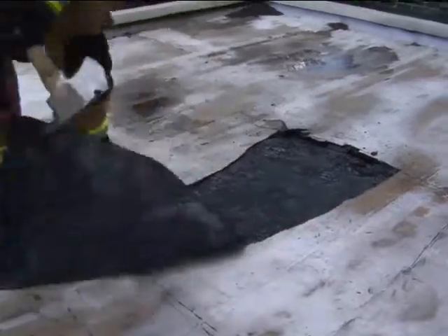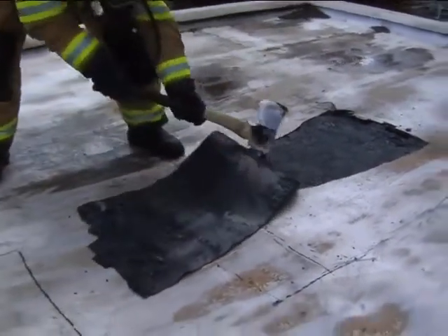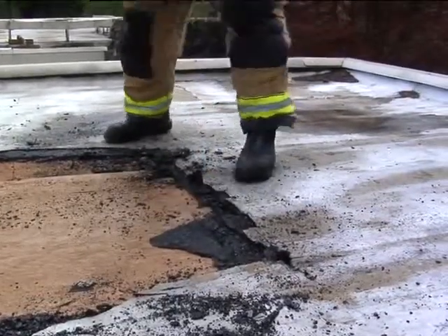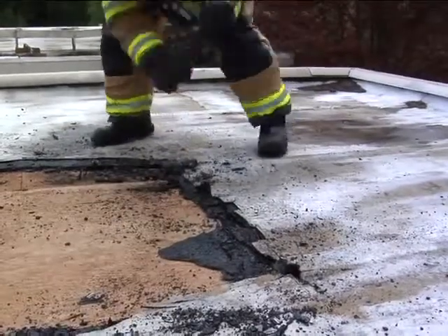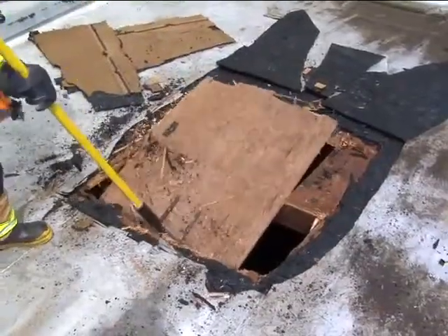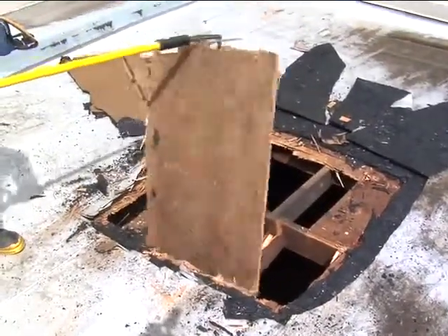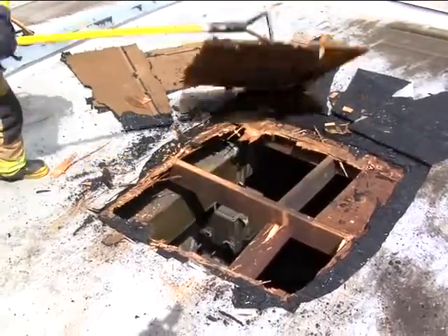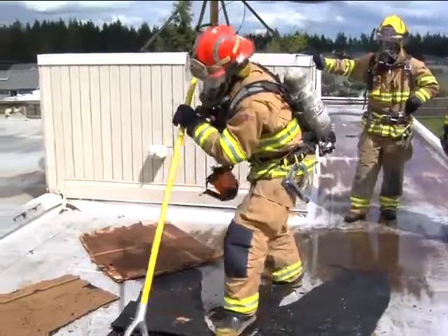Remove the roof material by cutting it and pulling it out of the way. Cut the wood decking diagonally along the joist toward the hole. Avoid cutting the joist. Pry up the roof boards. When the opening is completely cut, push the handle of your pike pole or plaster hook through the roof to open the ceiling below. Be careful of a sudden updraft of heat and smoke.